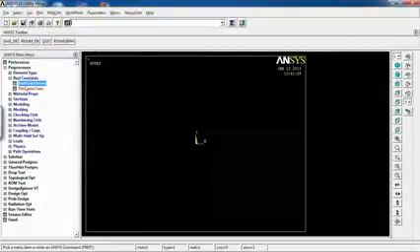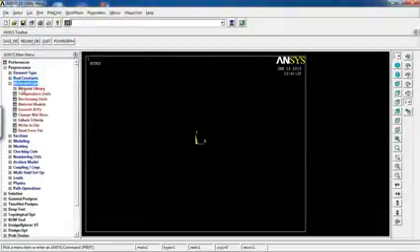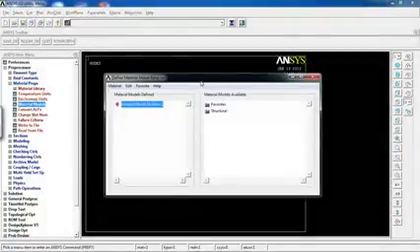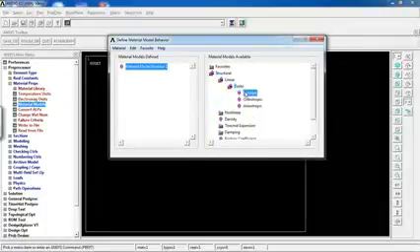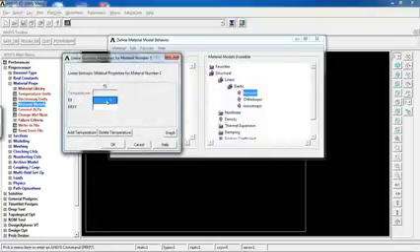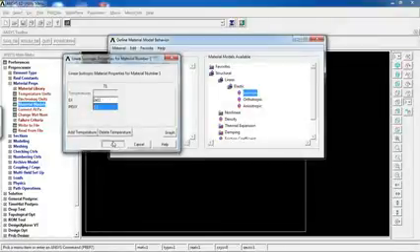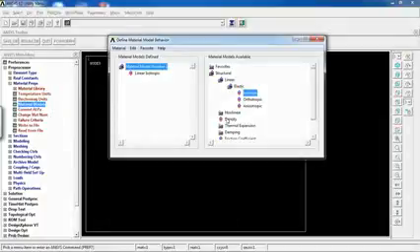OK, close the window, and I go to Material Properties, load Material Models. So one thing that differs in here compared to the previous 6 lessons is after I define elasticity of 200 gigapascals and Poisson's ratio of 0.3 and OK the window, then I have to define a density.